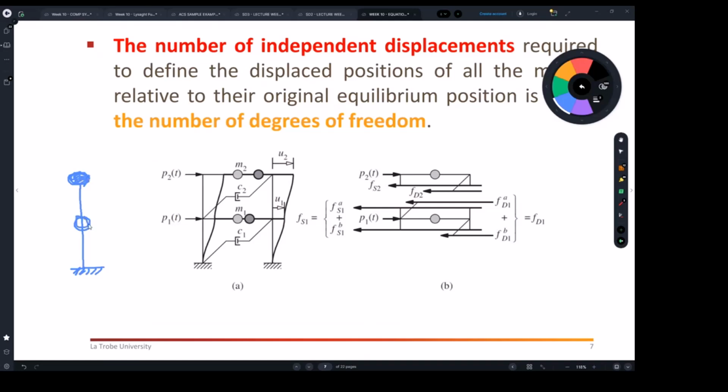And we're going to learn next week that it's got 2 mode shapes. One is the green, which is the whole building actually, where both floors go in one direction. So whether to the right or to the left, it doesn't matter. But the shape is actually 1. So that's the first mode shape.